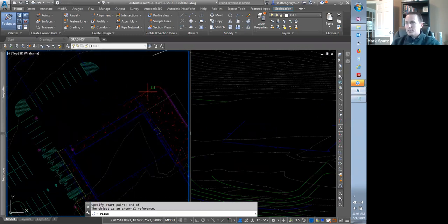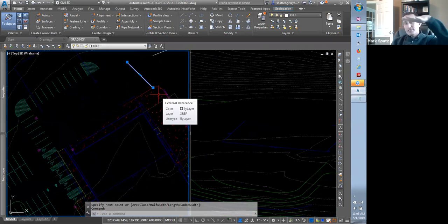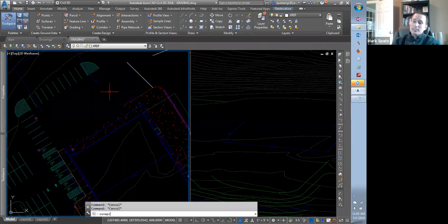So let's just use this, for example, this curb line. If I do my snaps to that, you can see if I hover over that node and look down at my coordinates here, although I'm at drawing elevation 608 because I set my elevation command, I actually drew that down at 0. Well, why? Because my OSNAP Z was turned off. So if I type in my OSNAP Z again, turn that back to 1, do the same thing.